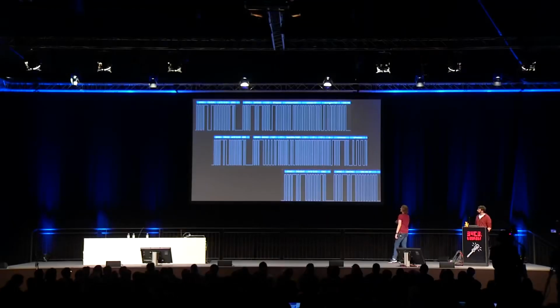So here we have a get descriptor request that's executing. It has a single packet that is transmitted back in response, and then we have an acknowledgement that the packet was indeed received. So we have the host sending get data, please, give me that descriptor. We have the descriptor being transmitted in response, and the host says, yes, I got this. Theoretically, it doesn't have to be one packet. If the device decides to respond with a very, very long packet, that could also theoretically be valid. So there might be multiple packets that make up a longer transaction. So let's say you want to send 512 bytes on a bus that has a maximum packet length of 64. That could be packetized and broken up into a lot of sequential packets.